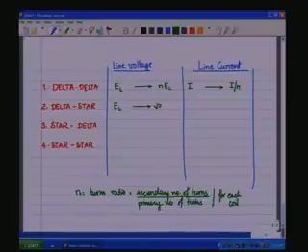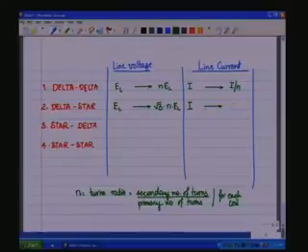So, root 3 into N into EL. If we apply a line current I, it becomes I by root 3 as the phase current in the primary side, it becomes I by root 3 by n, the current that is induced on the secondary side, and that itself is the line current on the star side, which is I by root 3 into n.